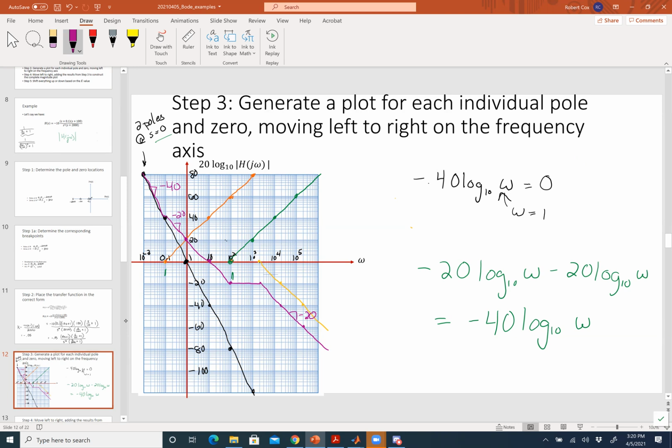I was just asking, for what we were talking about before, the magnitude at each point in dB would be whatever my y-axis value is. That's right. Now that's not the magnitude. I've got to un-dB that. I have to get that out of dB and into the true magnitude, which means I've got to do some more math, which we'll do in a second, once we get this finished up.